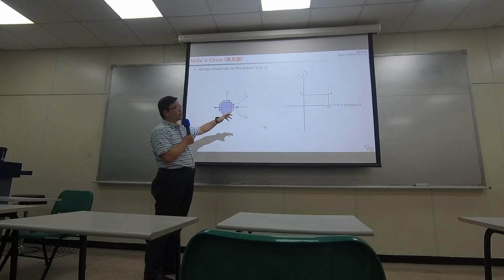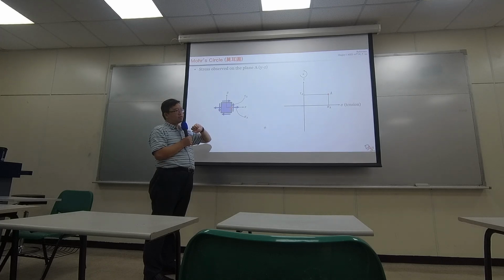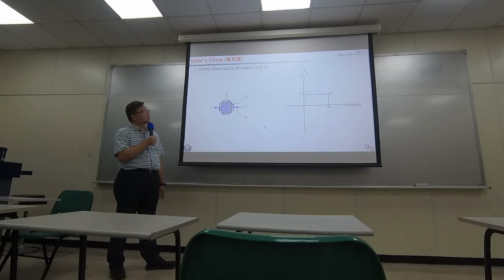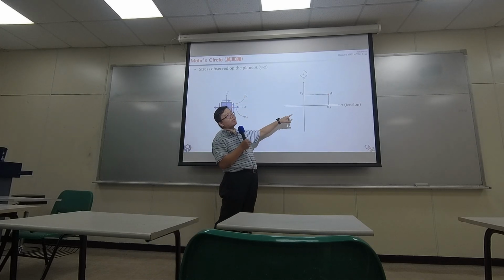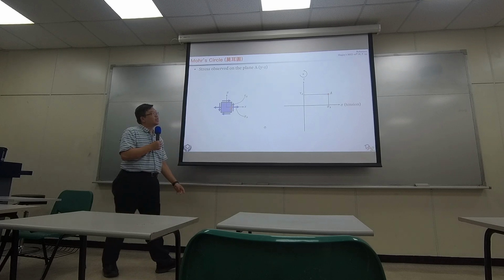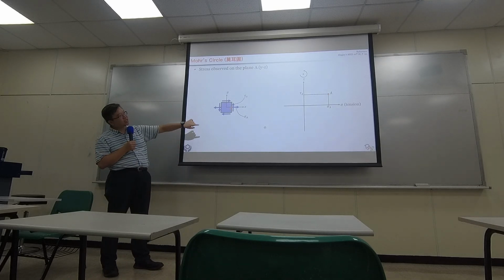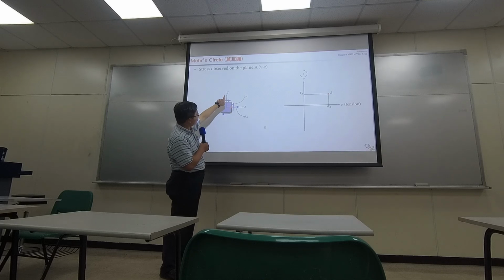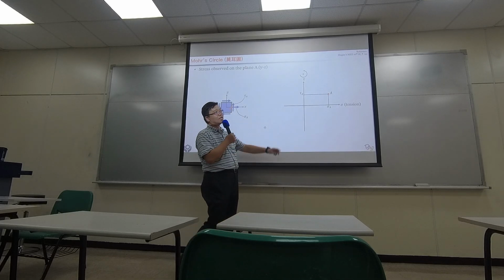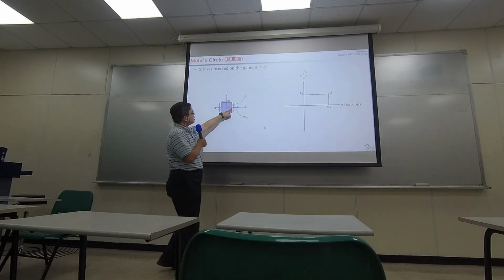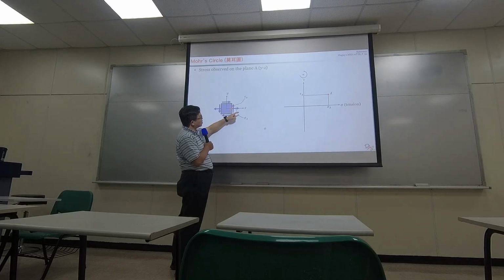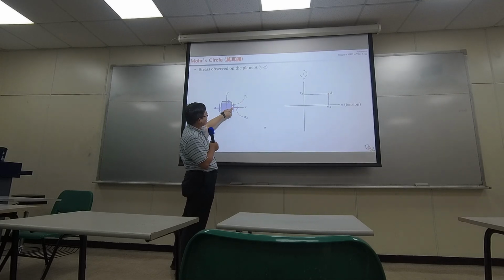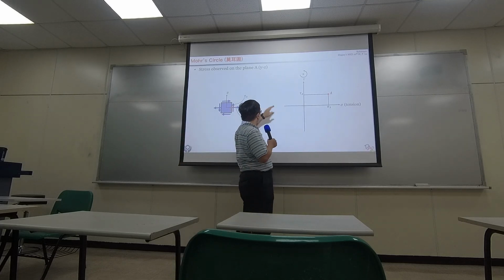Also, people use different ways to record the shear stress: some people like clockwise as positive, some like counterclockwise as positive. It doesn't matter. In my demonstration, I choose counterclockwise as positive. So whenever you see a shearing stress rotating counterclockwise about the center, we treat it as a positive shearing stress. Over here you can see there's a positive normal stress, sigma A, and a counterclockwise shearing stress, tau A, with some value. So these are positive values.